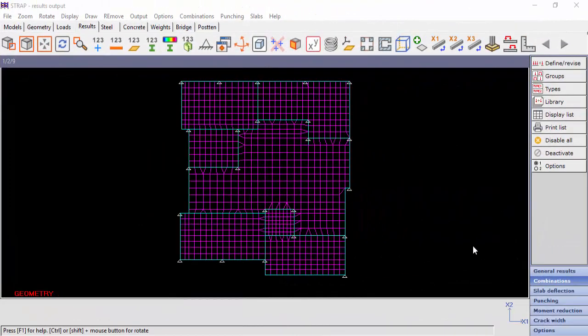For load case groups, we added an option to define a load case group that all loads in it will be multiplied by a factor. When generating a load combination with this group, the program will generate a number of combinations that equals the number of load cases in the group, and the factors defined in the combination table will be assigned to each of the load cases with every combination generated by the program.